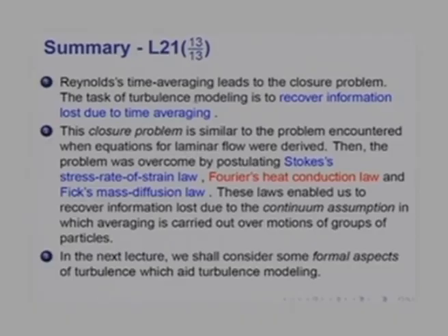Essentially, Reynolds time averaging has led to the closure problem, and the task of turbulence modeling is to recover the information lost due to time averaging. This kind of closure problem we have encountered earlier also in laminar flow, where we made a continuum approximation and we recovered the information lost in averaging over a large number of particles through viscosity and conductivity and so on and so forth.